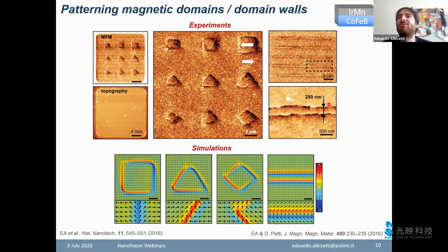This is the resolution given by the magnetic properties of the materials, which are limited by the width of the domain walls. These are the regions that separate two different domains. So the thermal profile can be much narrower, but the magnetic domains cannot be that much narrower because of the magnetic properties of the ferromagnetic layer.